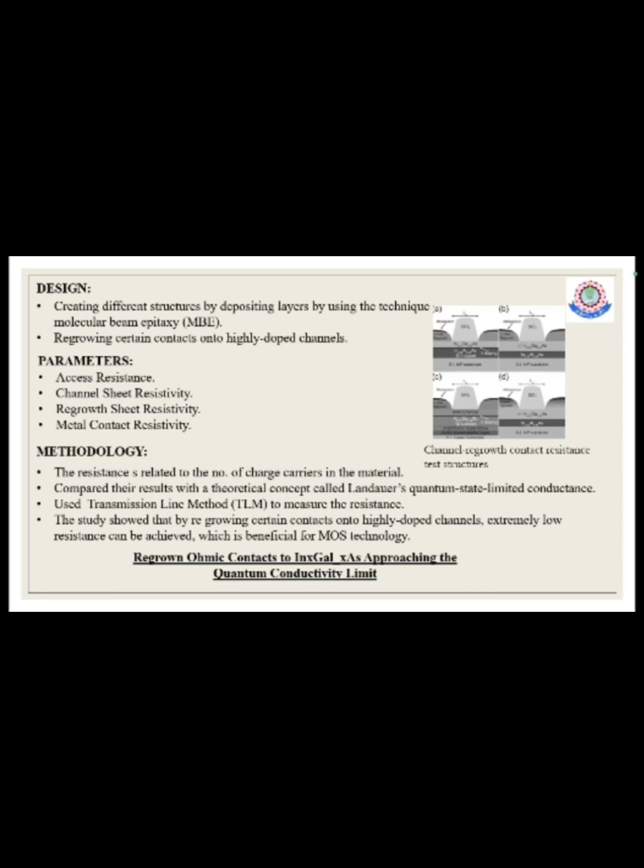They found that the MBE, molecular beam epitaxy method, regrowing the channel between the source and the drain leads to very low resistance in samples with a high number of charge carriers. So molecular beam epitaxy is very useful to increase the transconductance of the MOSFET.